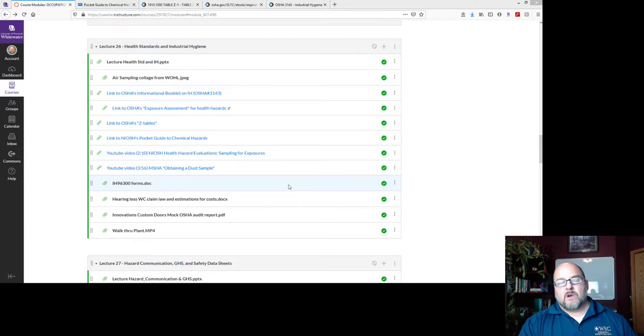And then every 45 minutes to an hour, you walk around and check your equipment and make sure everybody's okay. Sometimes you have to switch out sampling tubes or cassettes because you don't want breakthrough. You don't want to get them so full that it's 100%. You want it below 100% because then it's a more accurate reading. And then at the end of the 8-hour shift or whatever it is, you collect all your equipment, make sure all of your samples are properly labeled and under your control, and fill out all the paperwork. You drive back to work, post-calibrate, compare everything, and get your samples ready to be sent to the lab.